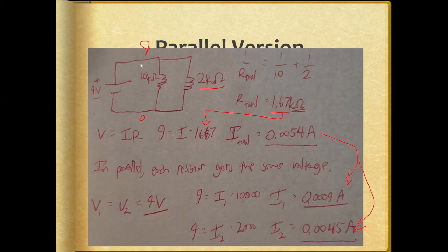You can use the power formulas to figure out how much power an entire circuit uses if you use the entire circuit's voltage, current, and resistance in your power formula. Alternatively, you can also use the individual voltage drop, current through, and resistance of specific resistors to find the power draw of specific components of the circuit.